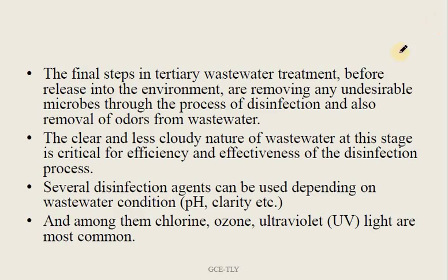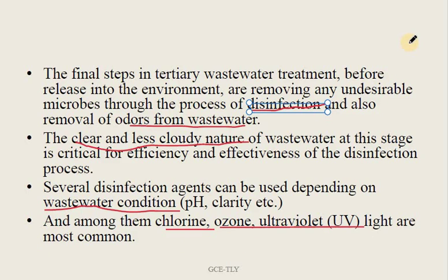So in the final steps of the tertiary treatment, before releasing the effluent into the environment, undesirable microbes are removed through disinfection, and odor removal is also carried out. At the end we get clear, less cloudy wastewater at this stage. Several disinfectant agents can be used depending on the wastewater condition. Among them we usually use chlorine, or ozonization, or ultraviolet light, which are the most common ways of disinfecting wastewater.